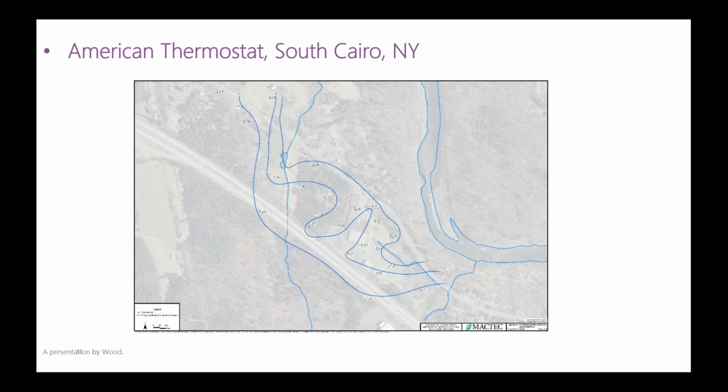So those wells that we have at the margins, the 2 supply wells for the mobile home park and the residential wells, all had that much of an effect on the system. They had put in wells that span the entire length of the bedrock aquifer, over 200 feet deep, and they decided that the residential wells that they hooked the residents up to the water system, those were open holes as well, so let's use those as extraction wells.